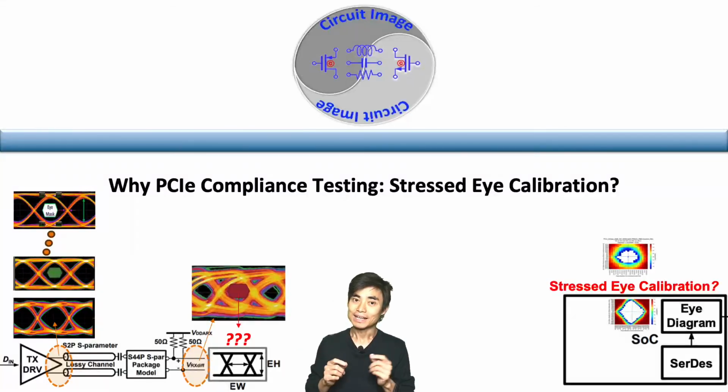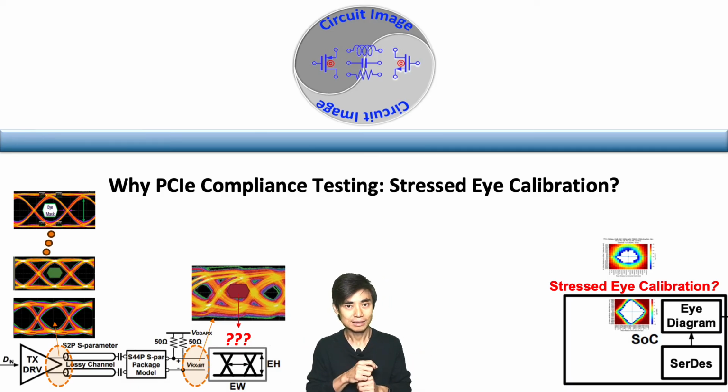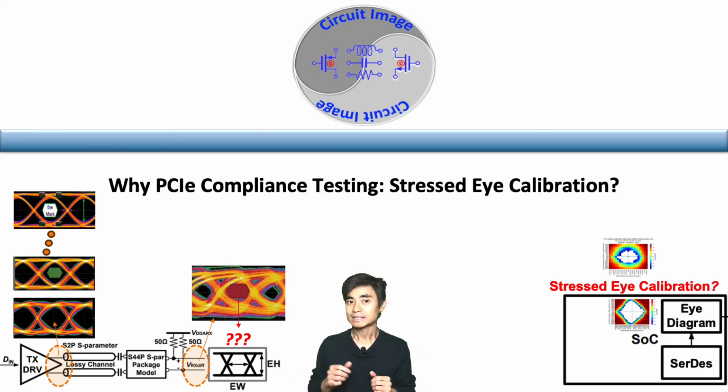Last time, in the white eye diagram video, I mentioned that there is no eye mask at the RX input, which is not true for some protocols, especially in the PCIe compliance testing of the stress eye calibration.